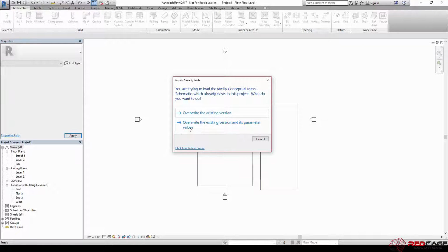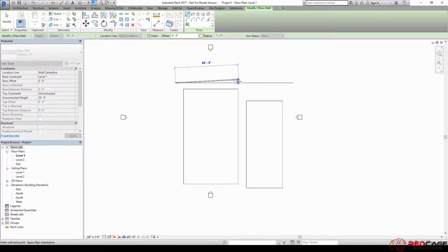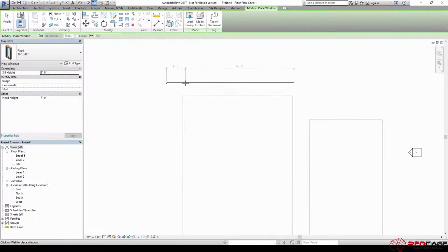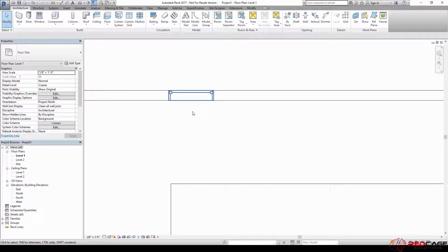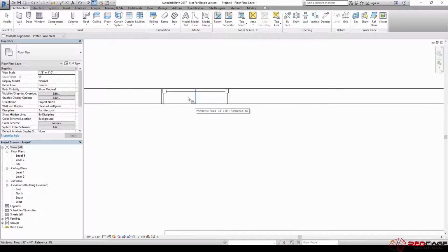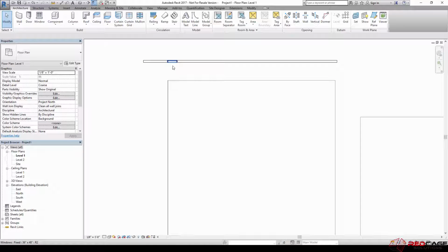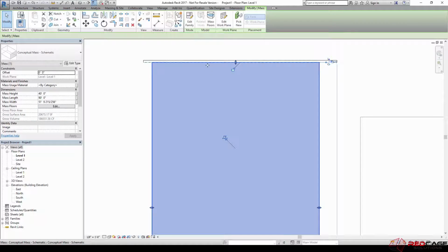To illustrate this, the reason why I wanted to show you this was because when we're looking at, say, a wall in a project, and we create a family, say we put a door or a window in that wall, when we hover over and we want to align things to these elements, you'll see these sometimes. Like that's my center, that's my origin reference plane. Or if I come over here, you can see that that's called reference R2, and we can tab around these things. If I hover over that one, that's saying the wall, but that one is for the void created in that window family. There are a lot of reference planes in any family, but if you name them, they'll have a little bit more specific behavior. That was just something I wanted to show you regarding these other families.